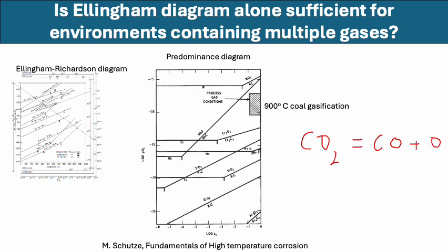And then we were only talking about the oxygen activity through this, considering this 2O to O2 equilibrium, and combining it and writing it in the form to find the equivalent oxygen partial pressure based on the partial pressure ratio between carbon monoxide and carbon dioxide. But there is also another reaction that is possible.